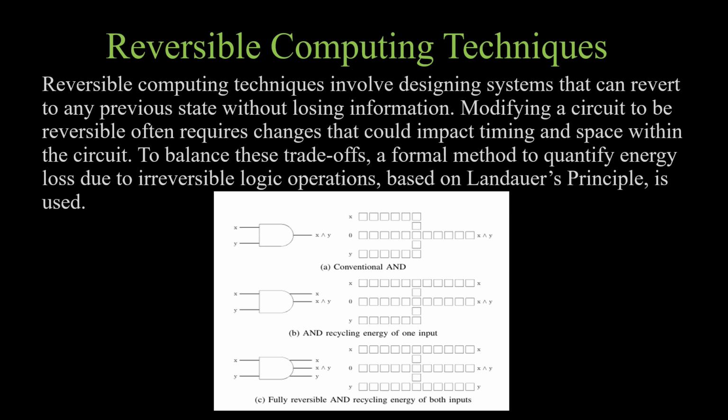reversible computing technique. The reversible computing technique involves designing systems that can revert to any previous state without losing information. Modifying a circuit to be reversible often requires changes that could impact timing and space within the circuit. To balance these trade-offs, a formal method to quantify energy loss due to irreversible logic operations is based on Landauer's principle. Landauer's principle states that the erasure of information in a computing process results in a minimum amount of energy